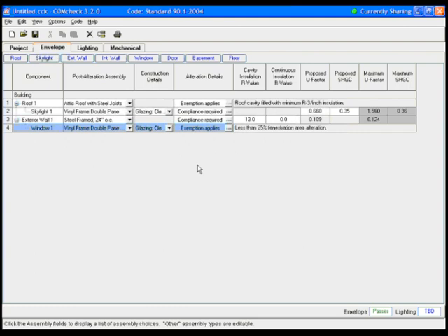Well, this is the basics of the building envelope. The components, if you do have an exemption, the criteria falls to the prescriptive tables. They'll either provide a maximum U factor on that component, or if it's glazing, it's going to provide a maximum U factor and solar heat gain that you need to meet. And then again, of course, you need to input your insulation levels for your roof, your exterior walls, if you had any interior walls, basement, below grade walls, and floor.